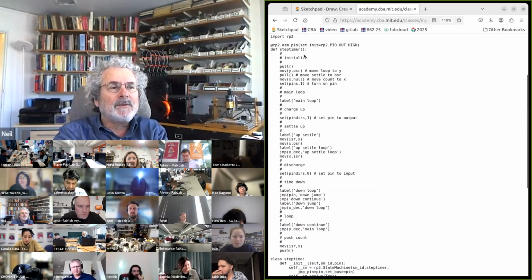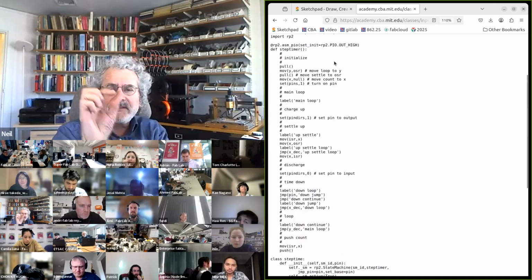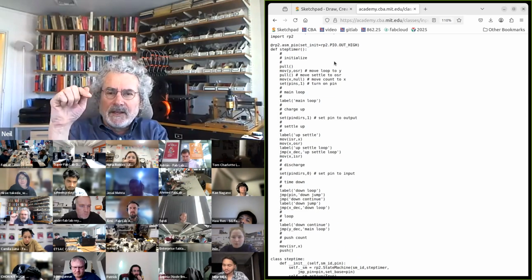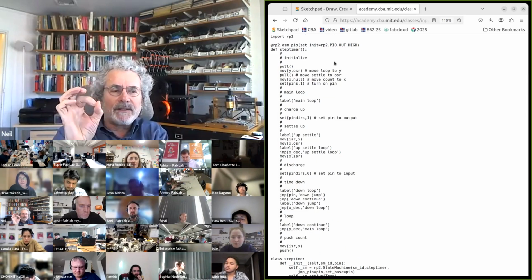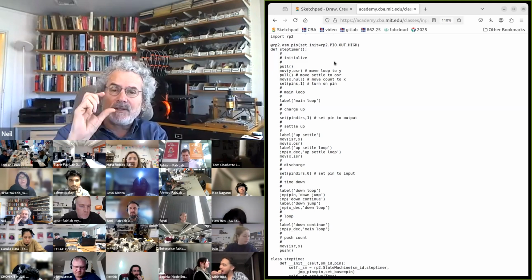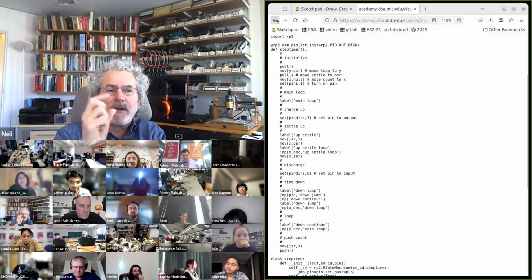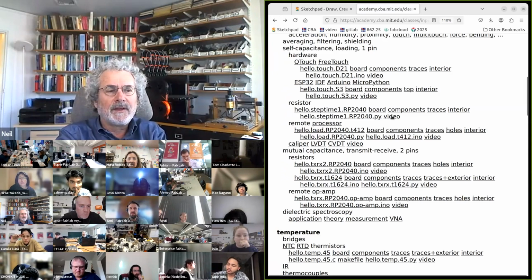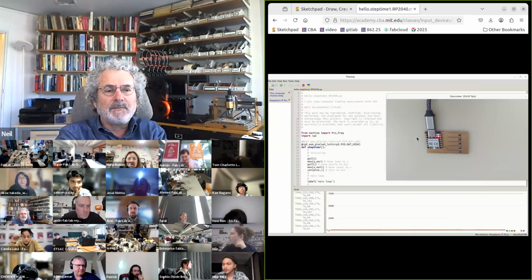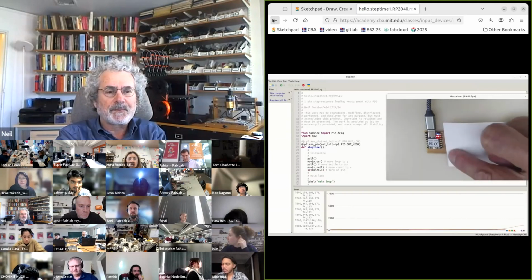And then what I'm doing here, and initially I don't expect you to understand this, is the little bit of code that goes into the PIO processor that tells it how to make the measurement of the charging and discharging. So here I'm building my own custom peripheral, and that then lets me read this on all of the pins to measure proximity.